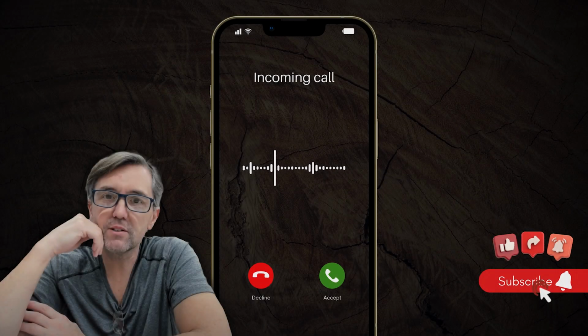So you've got a need for a custom threshold. We're talking about what's the overall height of this custom threshold and what's the wall thickness. The overall height is obvious. The wall thickness is, if you put a caliper on the aluminum itself, how thick is it? If your overall height is a quarter inch, that wall thickness has obviously got to be well less than a quarter inch because of that angle that you have on the piece. And if it's half-inch overall height, then you can make that wall thickness, more typically 3/16. That's going to work.